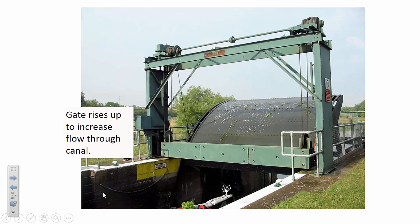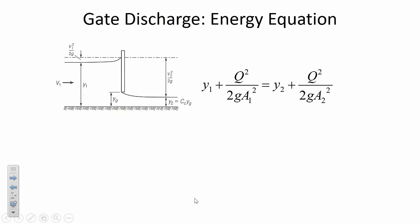And you'll notice that this is a rectangular channel that the gate is placed into. So in its simplest, you can use the energy equation to predict the flow under a gate like this. There are losses that we'll account for with a coefficient, but the energy equation is a starting point for understanding what's happening.